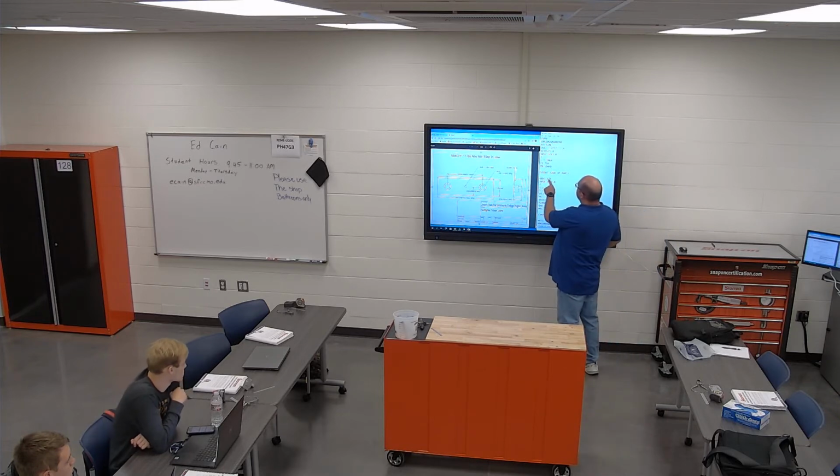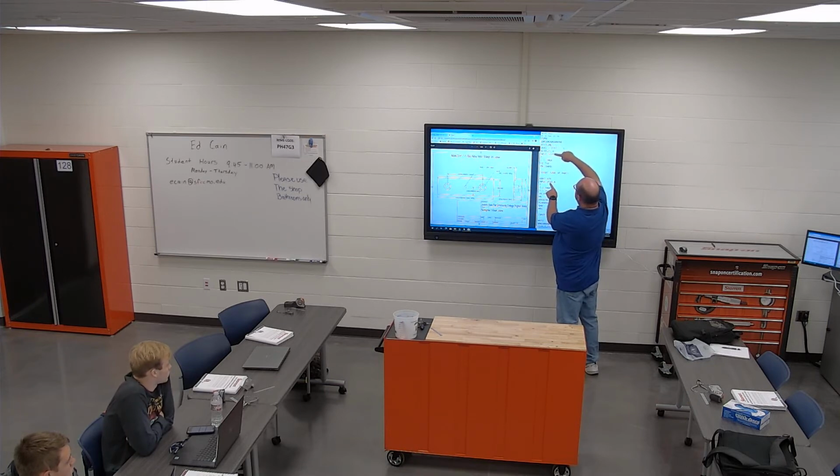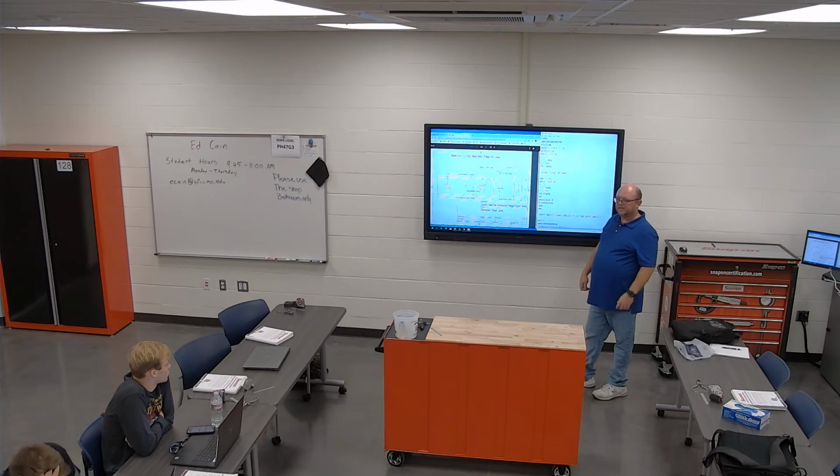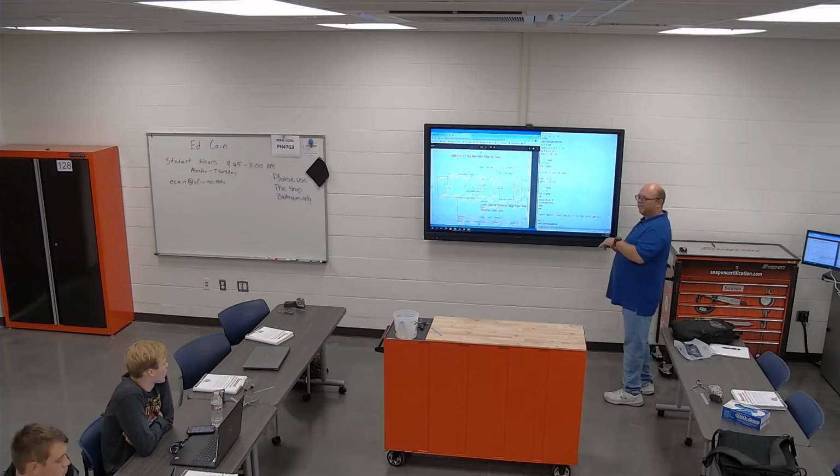Same way, G0 to the opposite of this, G01, Z.1, so I copied this line, copied this line, copied this line, and then that's the opposite, and you go back up. So I followed it, I go too fast. Your book will help you with the coordinates stuff, we can go over that later. I'm trying to refresh everyone's memory so that they can write their program.